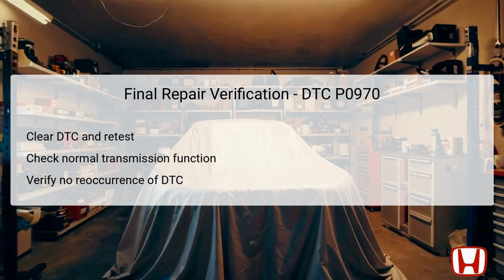Following this, conduct a road test or controlled driving session to check for normal transmission function. This should include shifting through all gears under various driving conditions to ensure proper operation. During this test, closely monitor the behavior of the transmission to ensure no abnormal shifting occurs. Lastly, check for the potential reoccurrence of the DTC.